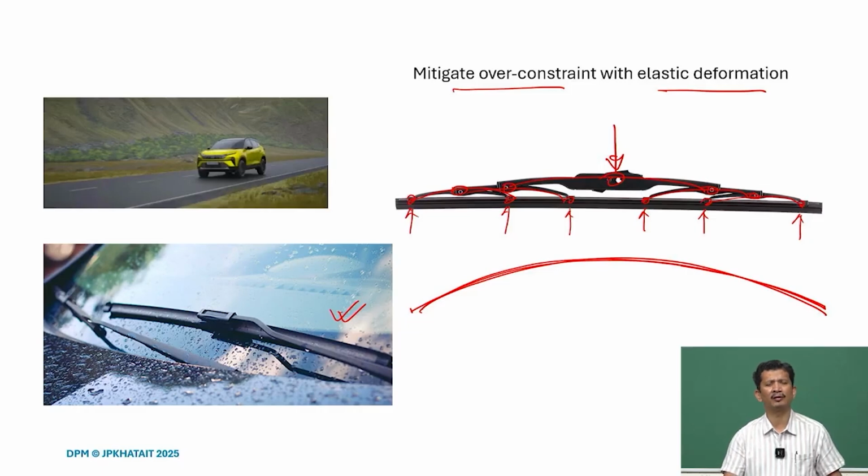So, if we are aware of these methods, I think many times we can replace the expensive items with monolithic designs, with plastic injection molded parts, with proper design, with the hinges, and we can get the same kind of performance.